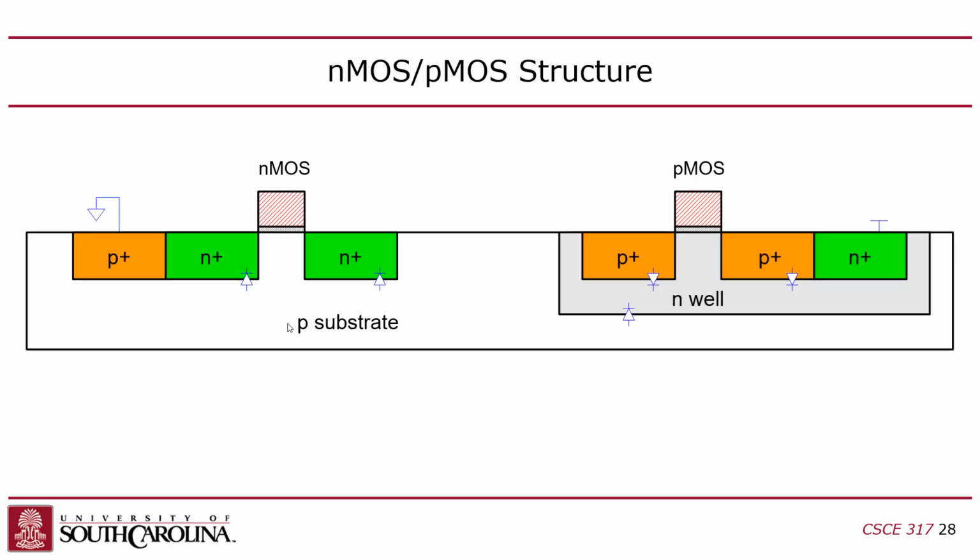Okay, so I mentioned this, that we've got these reverse biased diodes that form between the diffusion areas and the substrate, right? Now, what are the diffusion areas exactly with respect to a logic gate? Well, that's basically your output, right? The diffusion areas are the source and drain terminals, which are essentially the logic gate output. That's how the logic gate outputs, right?